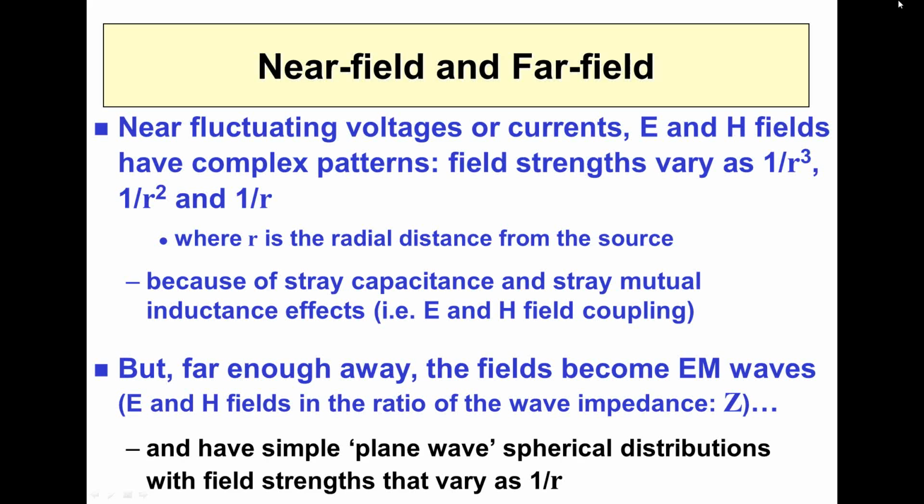Now, we're all familiar with emission tests, where you have a choice sometimes of testing at 10 meters or at 3 meters. And you can take the limit at 10 meters and add 10 dB and use it as a limit at 3 meters. I know it's a bit crude. And people argue about whether it should be 8.5 or 11.1 or whatever. But anyway, it's a spherical distribution, or hemispherical in the case of a measurement over a ground plane. The field strength varies as 1 over r.